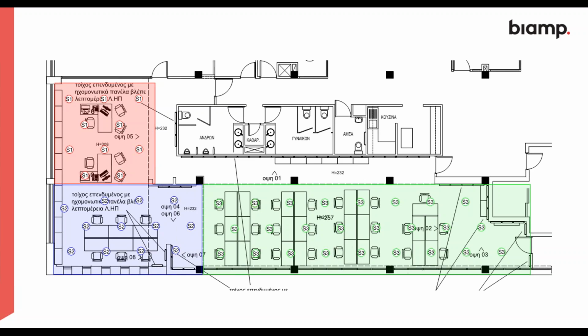Is it possible to increase the input sources? No, you cannot increase the number of input sources on the standard controllers. How we would get around that is we would duplicate controllers, and then that gives us more input zones.